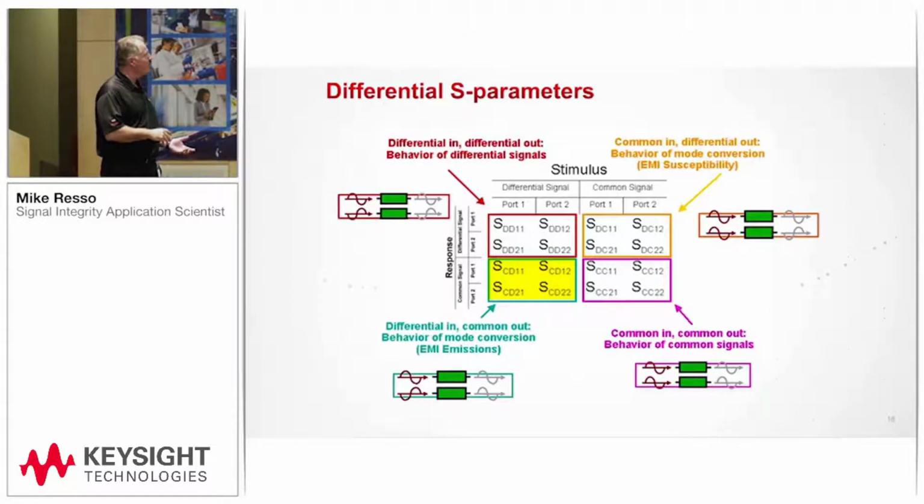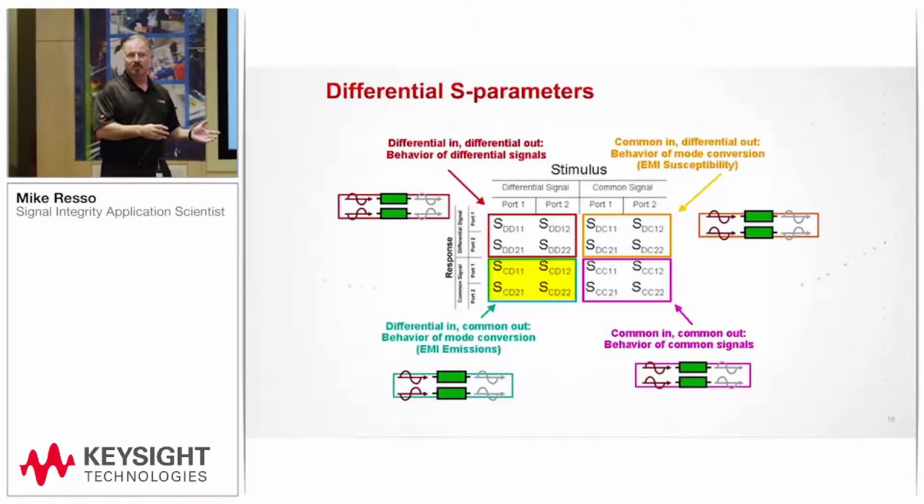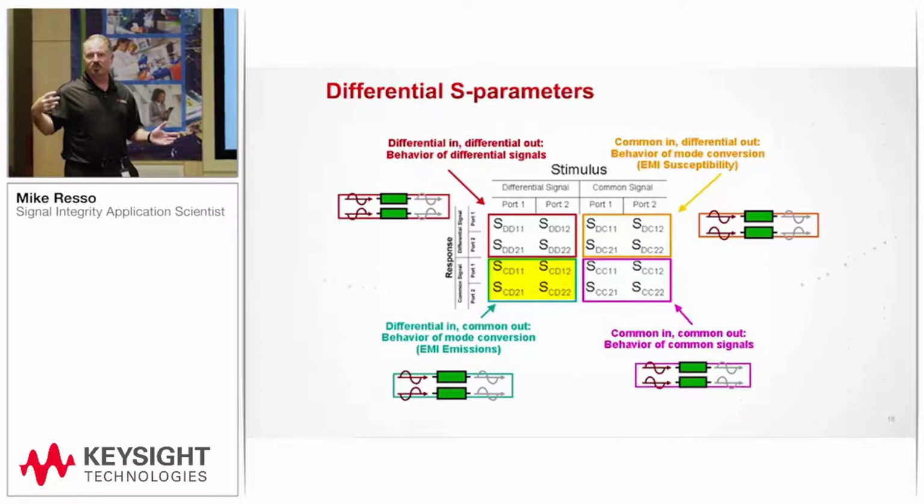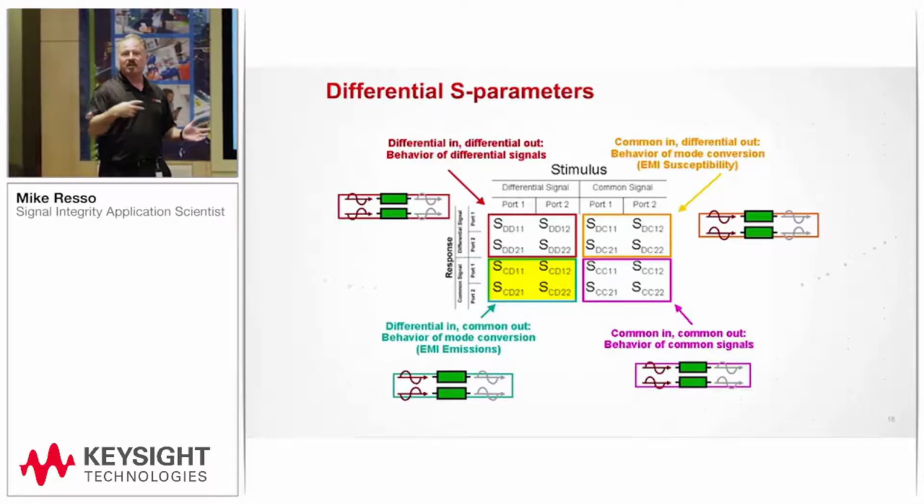being converted. This would be if, say, you have that same asymmetric differential line and your signal from your transmitter is propagating a good differential signal through it, but now you encounter that same site where you had that asymmetry. Well, there's going to be an impedance discontinuity there, so you know there's going to be a little bit of reflection, but you can also have some of that differential energy converted into common, and now that site will radiate.